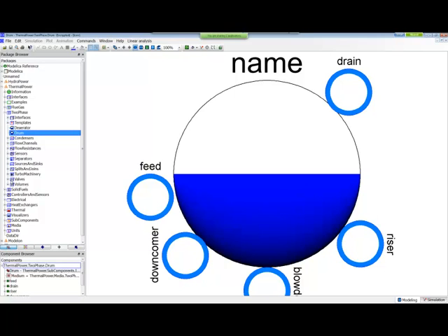Like in flue gas, there are valves models, volumes models, etc. There's an open volume model, like a tank model, included here. Under turbo machinery, you will find the compressor model, pumps models, and the steam turbine model that are based on the Stodola law.